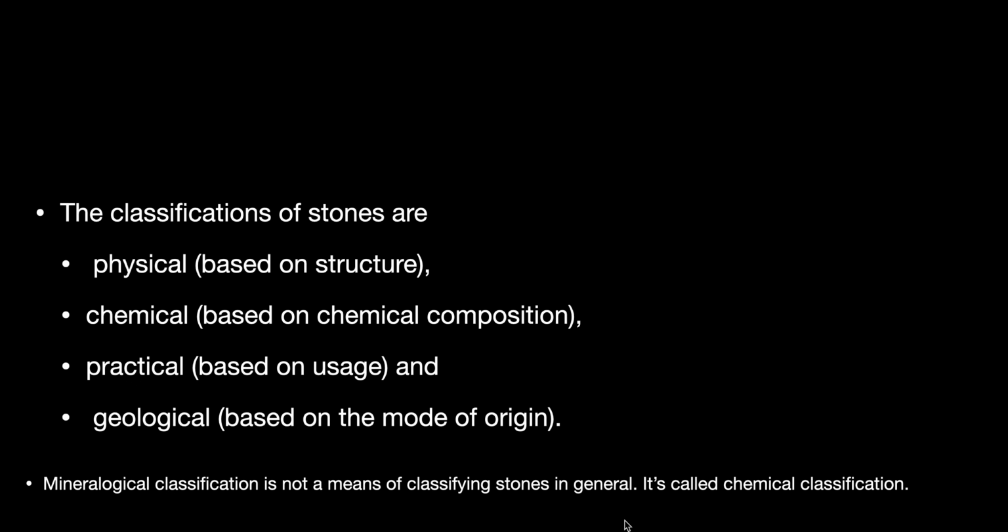So coming to the classification of stones, which are physical based on the structure, chemical based on chemical composition, practical based on usage, and geological based on the mode of origin. Read it again. Physical is based on the structure of the stones, chemical based on the chemical composition, and practical is based on the usage of the stone, how we are using it. Geological is based on the mode of origin, and mineralogical classification is not a means of classifying stones in general.